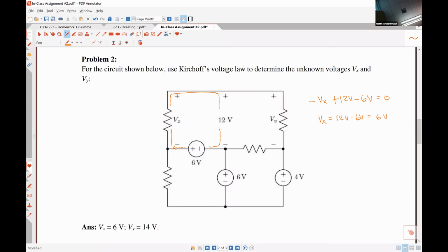One thing that troubles students, and I think I mentioned this in the video lecture, is this bit right here. This voltage is simply the potential difference between this top node and this middle point of the circuit. It doesn't have to carry current or anything like that. As long as there is a difference in electric potential, there's a voltage that we can deal with.